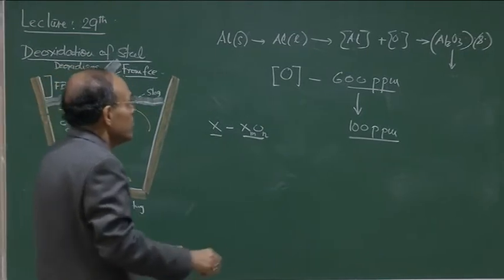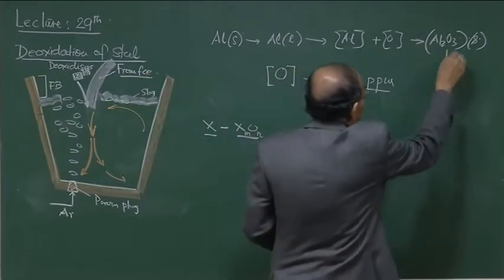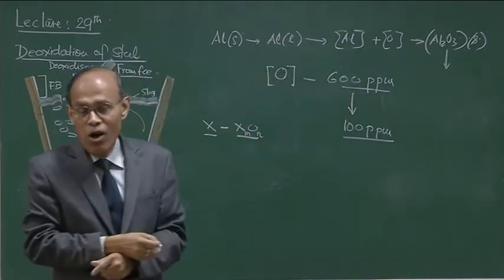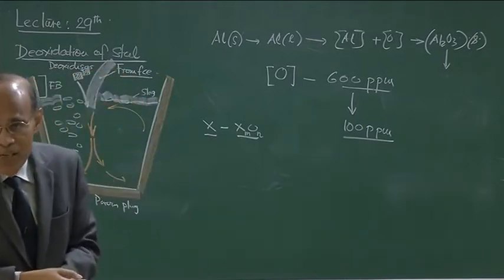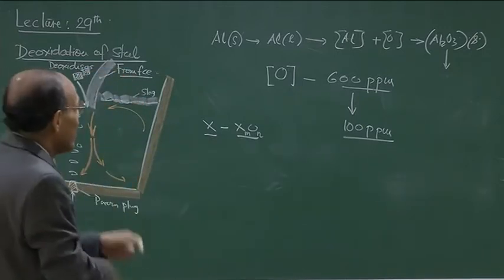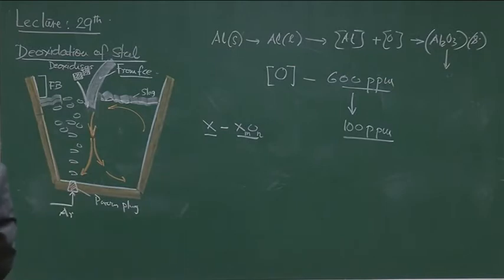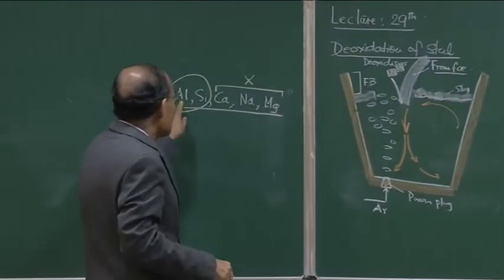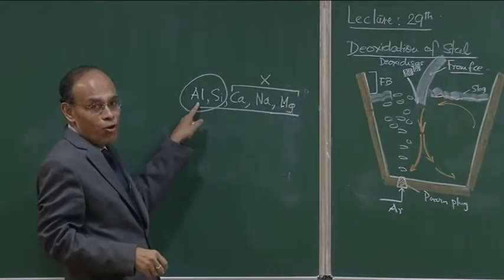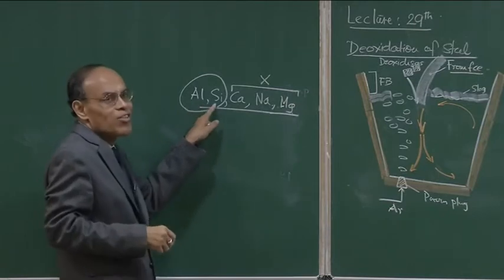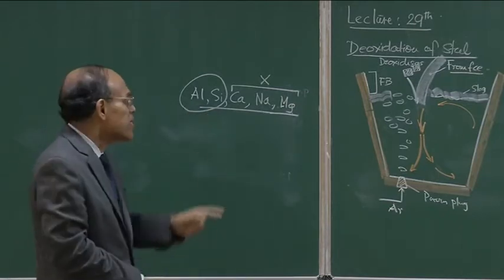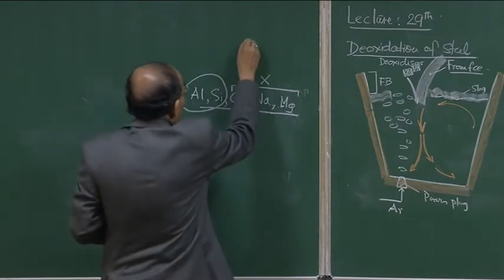Okay. So nucleation and growth is a characteristic of the deoxidation process, because we form altogether new phases. Silicon, for example, while aluminum is going to be added in pure aluminum form, commercial aluminum, silicon is never added as pure silicon. Okay. Silicon is added as ferrosilicon.